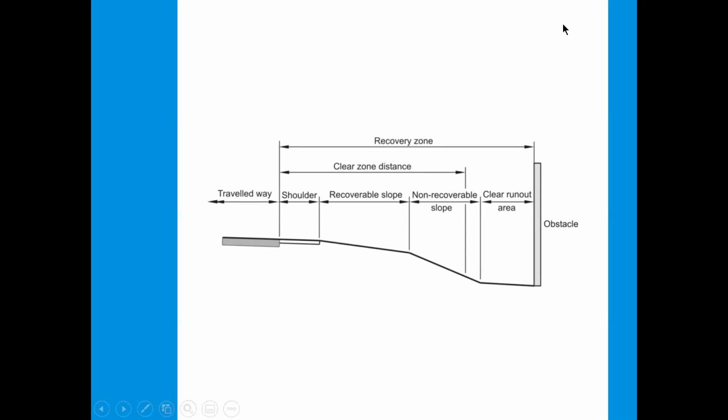Other measures to make roadside hazards more forgiving include considering the mature trunk size of trees prior to planting, avoiding horizontal fence railing to reduce the risk of spearing, and installing drivable culverts and walls.